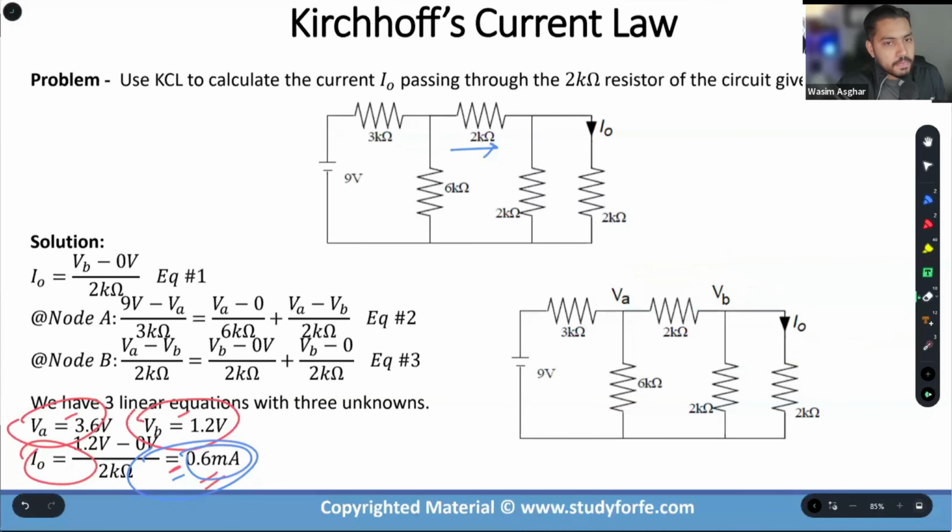So as you can see, KCL is no rocket science. It just requires you to carefully manage the circuit with the assumptions, with the equations, and do the proper analysis, use Ohm's law, be careful with the higher voltage, the lower voltage, the delta V, collect all the incoming currents on one side and the outgoing currents on the other side, and then analyze it and solve it. But there are multiple tripwires throughout this, starting with passive sign convention, being consistent with your assumptions and so on.